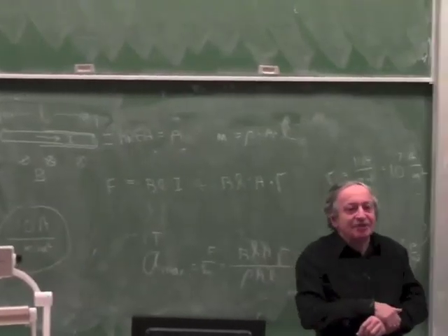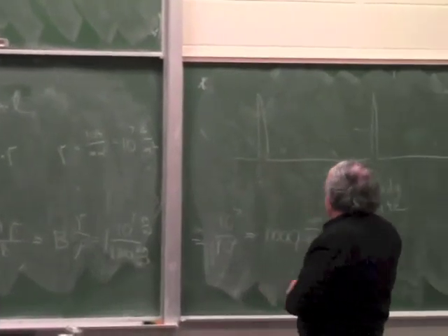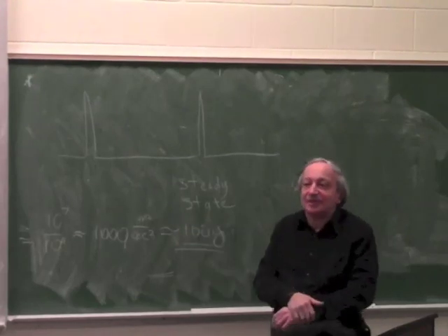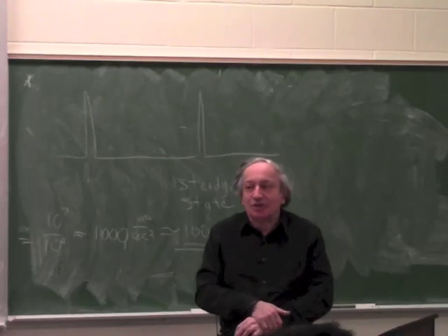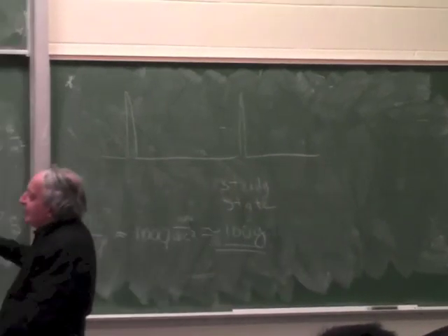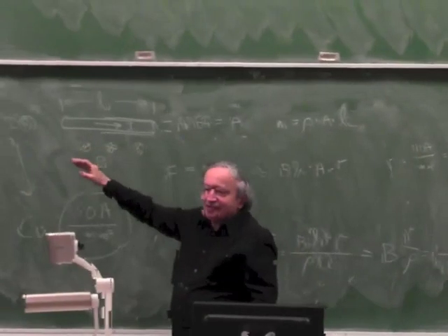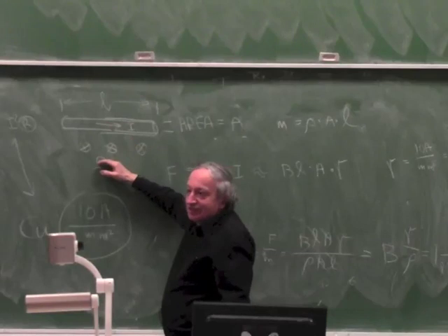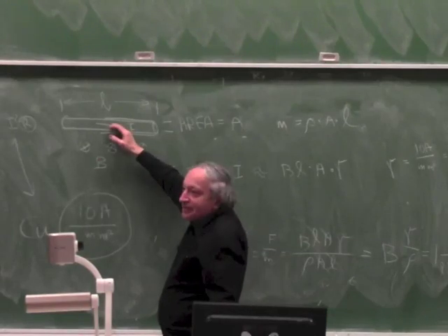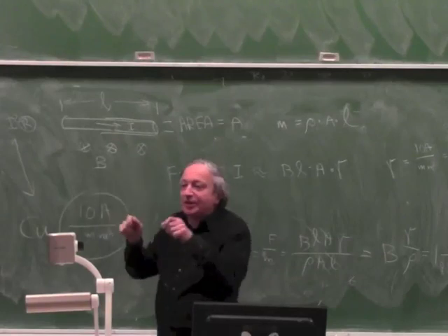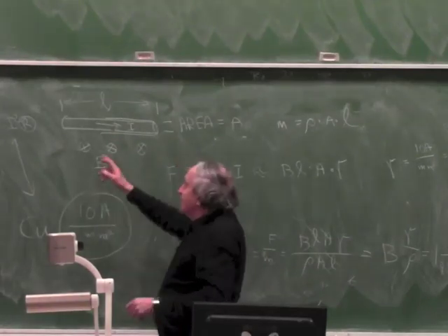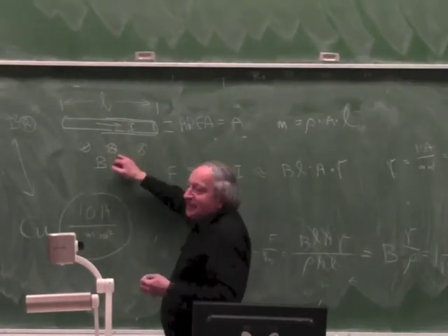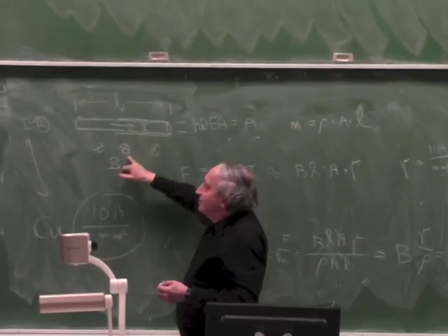But there is a very real limit which prevents us from going, say, 1,000 times this value. You can go maybe 10 times this value, but not 1,000 times this value. And that limit is demagnetization. Because when I drive that current, I started this lecture by saying the way I get a force is that the current creates a magnetic field. The magnetic field this current creates interacts with this magnetic field just like when you hold 2 magnets together. The force I get is like the force between 2 magnets: the magnet created by the current and the permanent magnet.